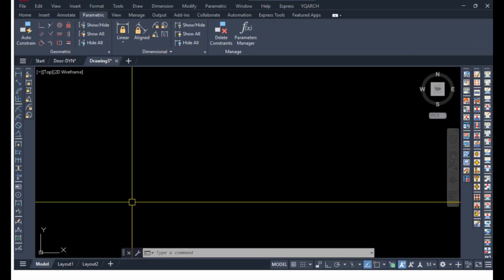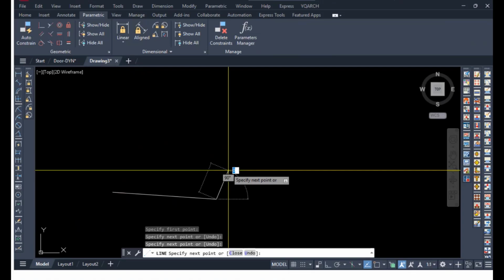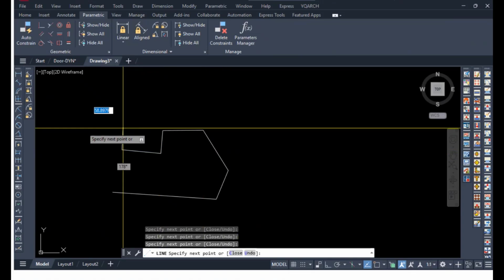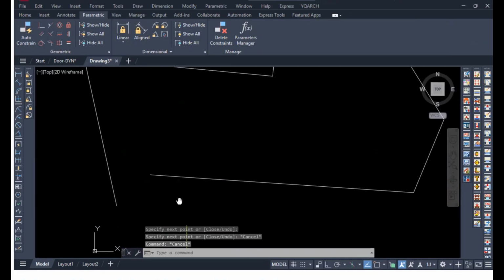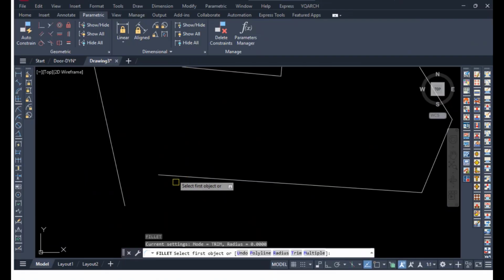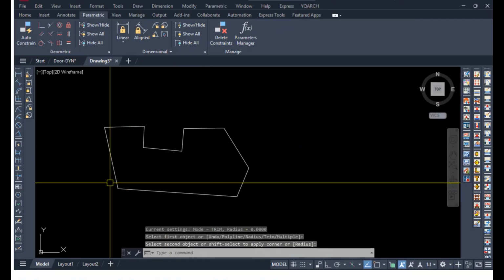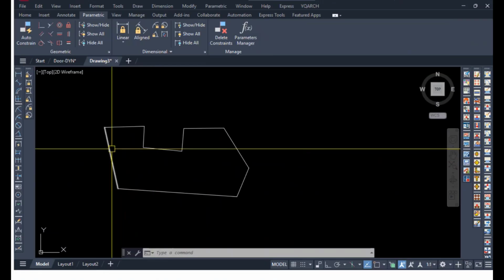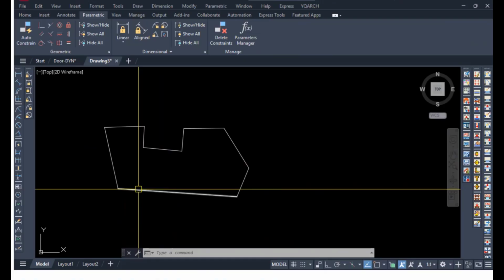First of all, for example, I write something messy here, drawing a very unaligned line. I want to close this one. The technique is that I use the fillet and hold the Shift key here. We can make the corner easily like this. So this line I need to be vertical, and this one we call a horizontal line. How can I do it?